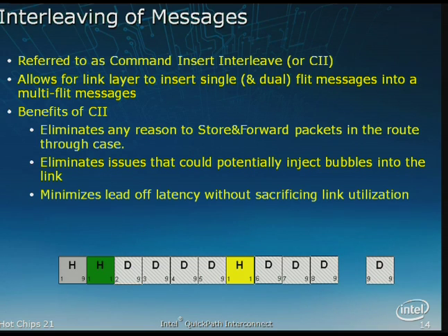One of the benefits of doing this is that the first data arrives, giving you your lead-off latency, but then you can shorten the latency of other transactions by injecting them someplace else in the data stream. And lastly, anytime so needed, we can inject a link layer flit. Retry is probably the best example here, saying the link going the other way had a CRC error and a replay is needed from point X.